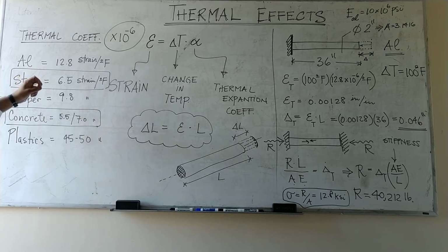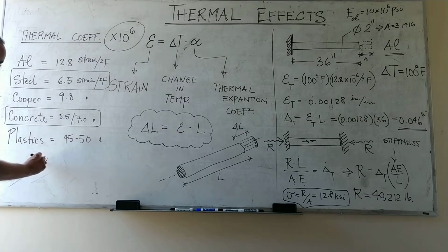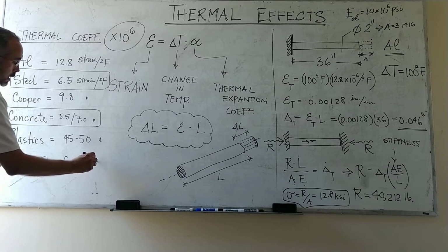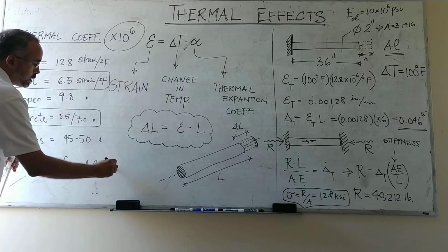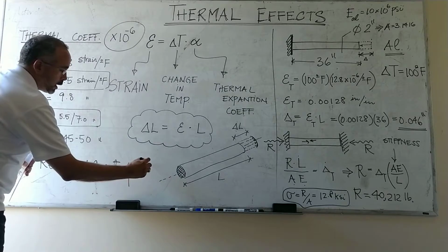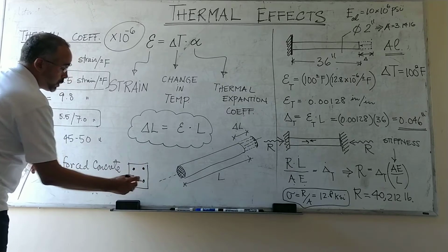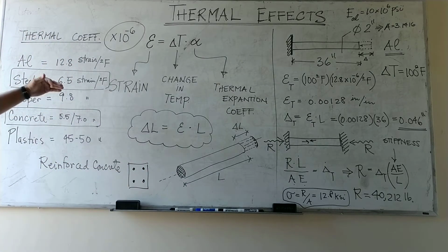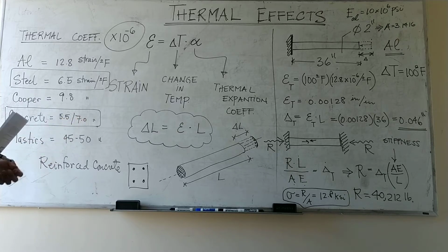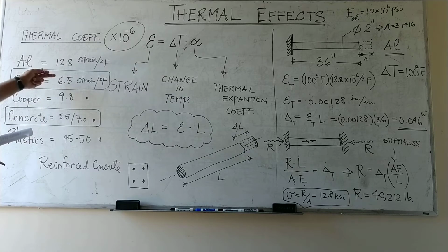That is very important because in the case of reinforced concrete, you have these two materials combined, like in a column where you have steel bars, and if those thermal expansion coefficients were very different, reinforced concrete structures would suffer tremendously due to changes in temperature, which could make them really unfit for use if this difference is too high.